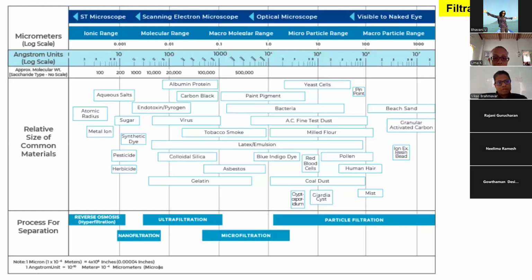So say we go to Kanakpura Road, right? If there is a lake and the lake is completely contaminated with organic and inorganic contaminants, and you have a tanker water or a borewell next to the lake, you end up having different types of bacteria. 1 micron filtration might not work. So you might have to remove a specific cryptosporidium, which is 1 to 10 micron, or any specific virus, which is even smaller, 0.01 micron. So we should be sure on what product to use for different contaminants, right?